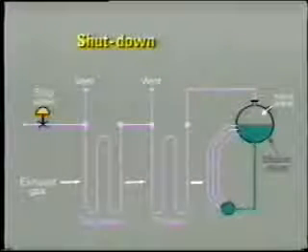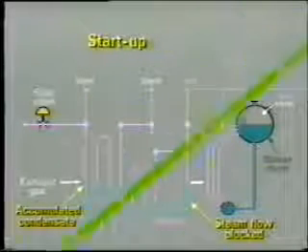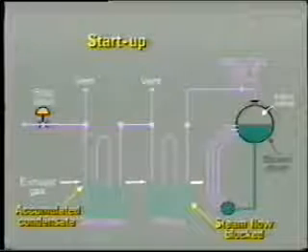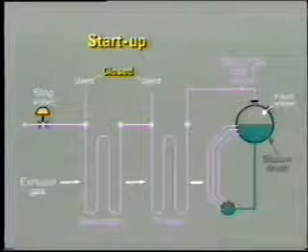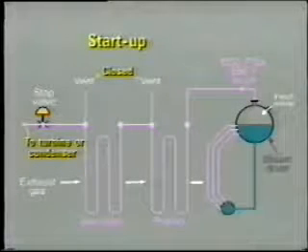After a shutdown, any steam remaining in the superheater tubes will eventually condense and actually block flow of steam through the tubes. This could cause overheating of the superheater tube metal during startup if gas flow and temperature are not well controlled. The only way to dispose of the condensate is by evaporation as heat is added. The superheater vents and drains should be left open until steam flow is established through the tubes. That is, either by placing the steam turbine on load or by directing the steam through the bypass to the condenser.